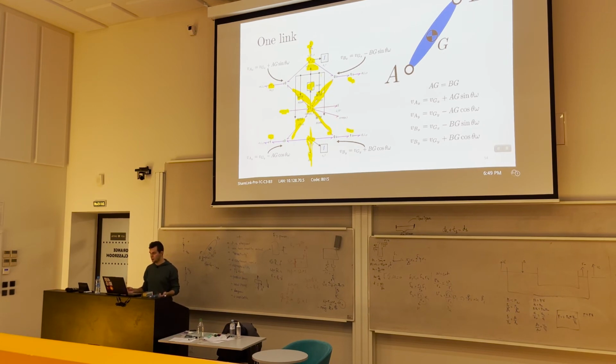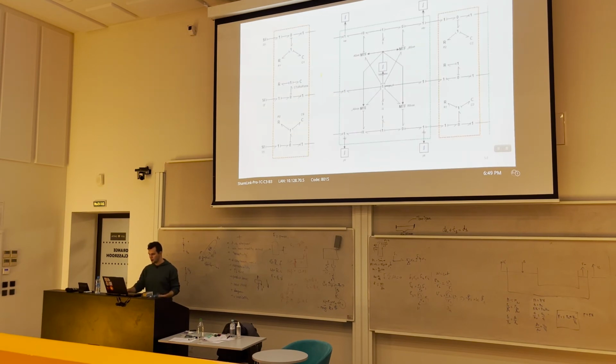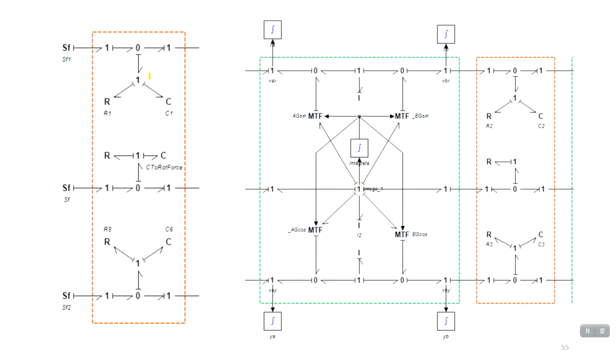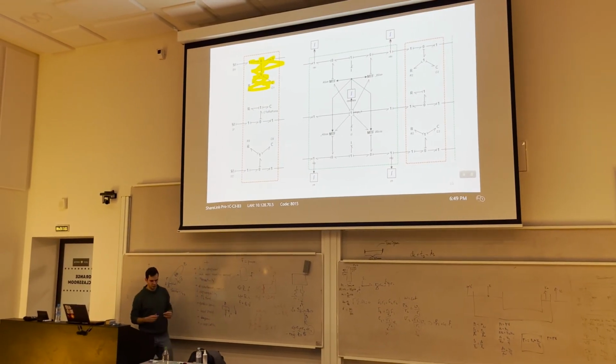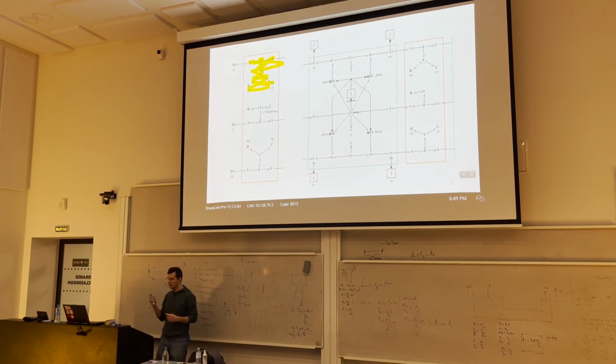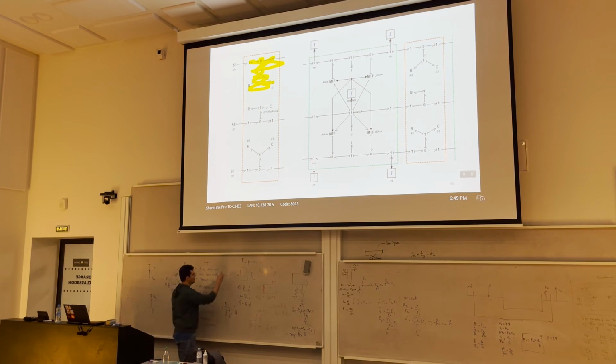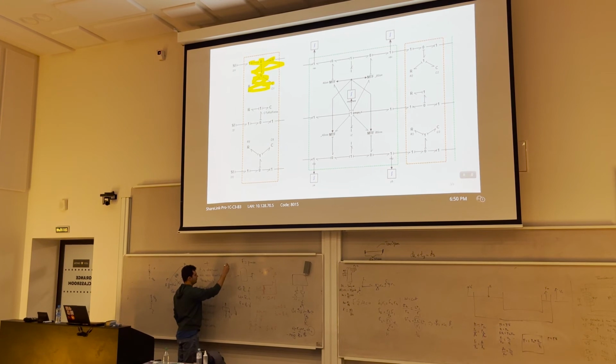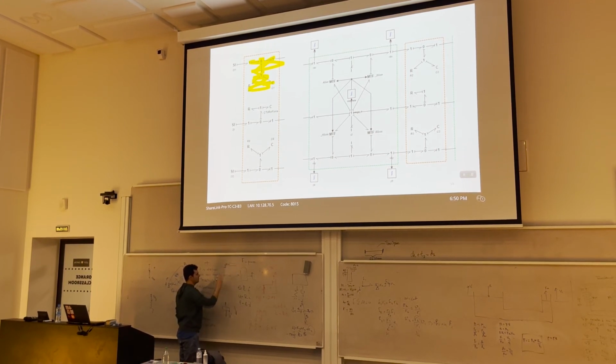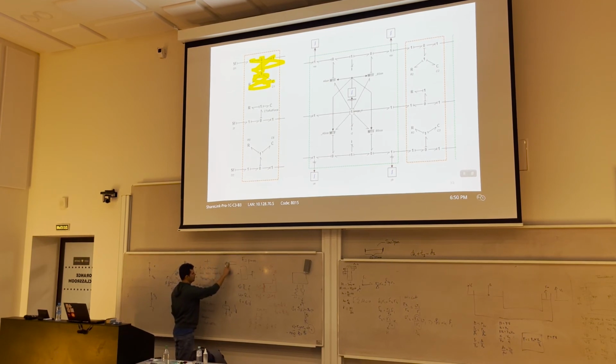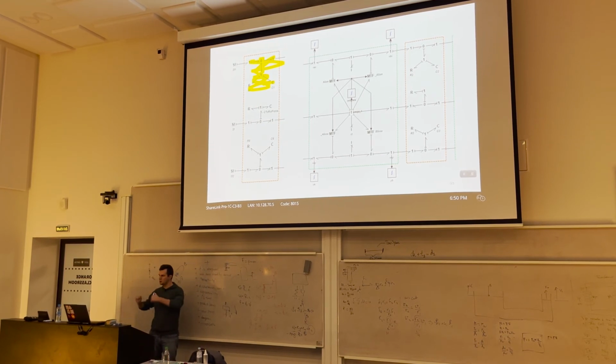Okay, so this is the way we model a rigid body. As for the joints, you see we use this structure. It's like we put a spring and a damper in a joint. It's like we have a body with a very stiff spring for the x component. Let me rewrite it. A very stiff spring for the x component and for the y component. It prevents motion along x and y, but it allows us to do the rotational motion. Okay?